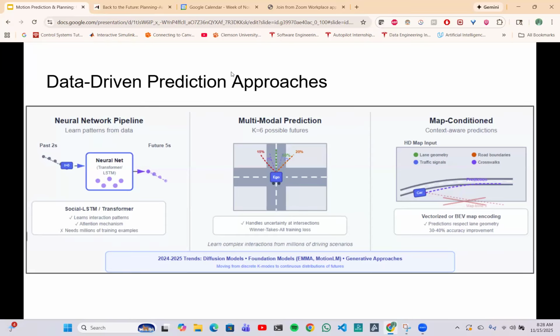We have some of the tracking already made, the predictions, the classification of the objects, and then you take them, and you have a neural network which takes that in as your input vector, and then makes a future prediction with multimodality. So it will not have just one output, but multiple outputs, and it will have time sequence information of those outputs. This is where a standard neural network probably does not do well, because there is a coupling in time.